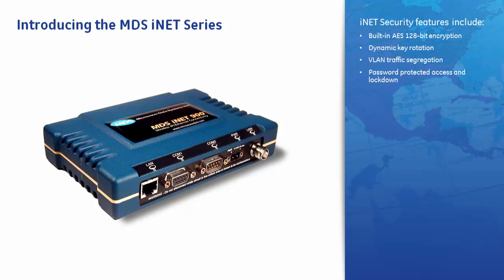Security is an important consideration with any industrial wireless solution. The MDS iNET series leads the field in this area with built-in AES 128-bit encryption for the iNET-II and RC4 128 for the iNET, dynamic key rotation, virtual LAN segregation, and password-protected login access. These measures, in addition to its frequency-agile transmission, make the iNET series an extremely secure choice for wireless signaling and control. Now, let's talk a bit about the two different models of iNET radios, the basic iNET and the iNET-II.